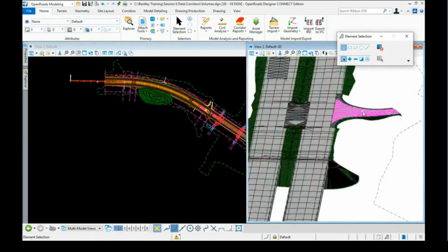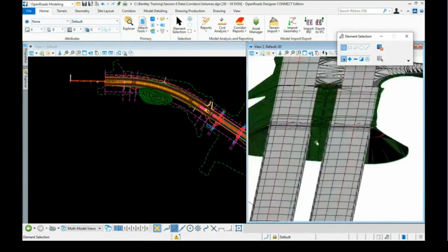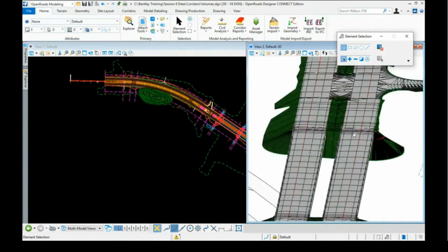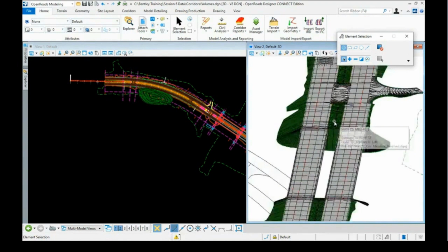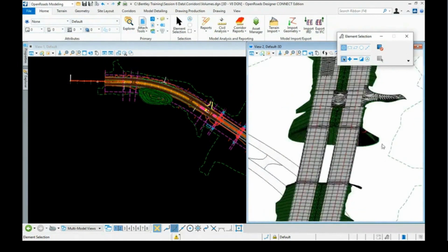And this is Scott last week when he did his bridge abutment. He used some linear templates. He used some surface templates. He used different methods. So it doesn't really matter what methods you use when you're modeling, as long as you get a good 3D model in the end, the volume calculations will query the 3D. So the more time you spend and the better your 3D model is, the better your quantities are going to be. Okay. So there's just a look at it in 3D.